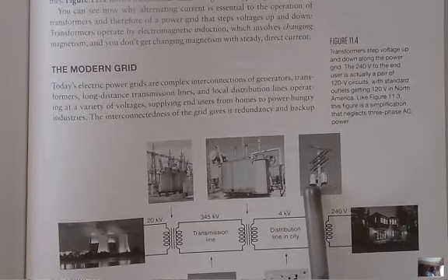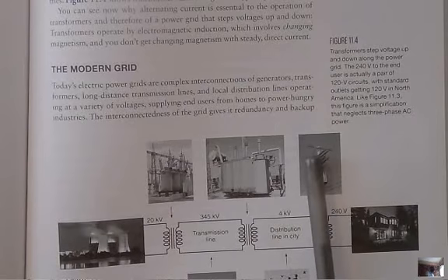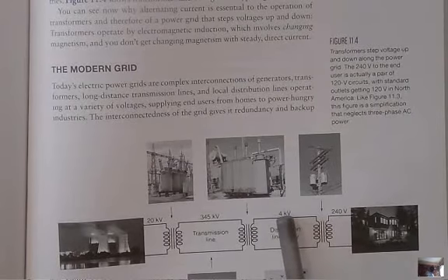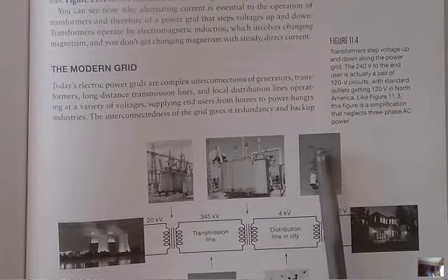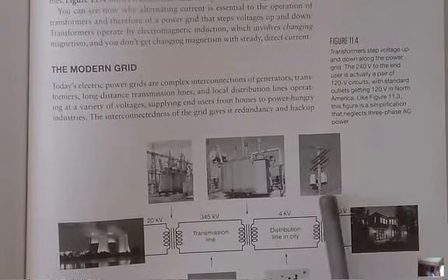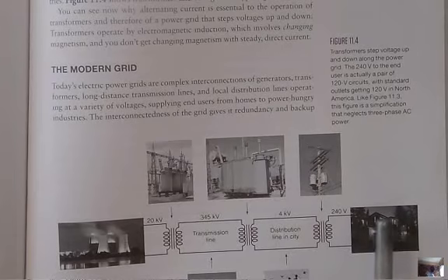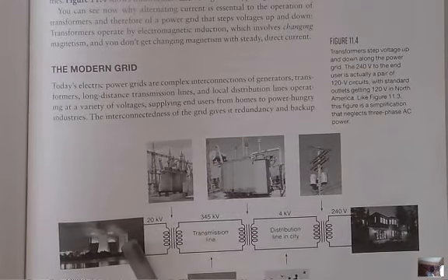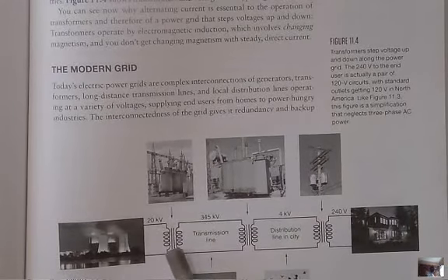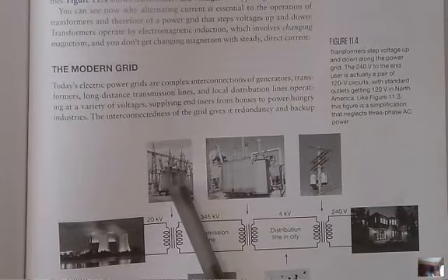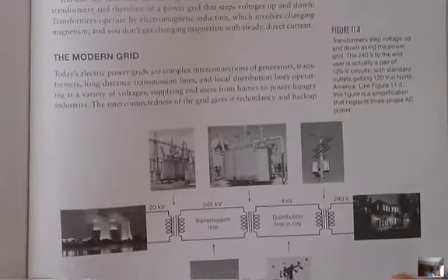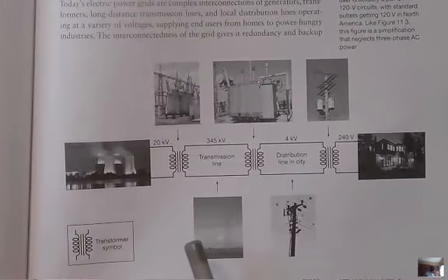These transformers, which look like cans sitting up there, take it from 4 kilovolts down to 240. The 240 comes off of there down into your house. So it's a long way from the power plant, with three transformers. Here's the first ones, and then they get transported.